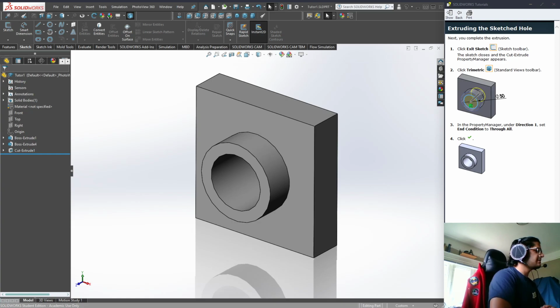Don't edit it there, because that might be the radius. Oh. What do I want it to be, diameter? Yes. So we're going to click check mark for the circle. That's not the check mark. Top left. Yeah. And now we're going to click smart dimension. Click the outside of that circle. Outside of circle, yeah. Click the label, set it down somewhere, and then 50 millimeters.